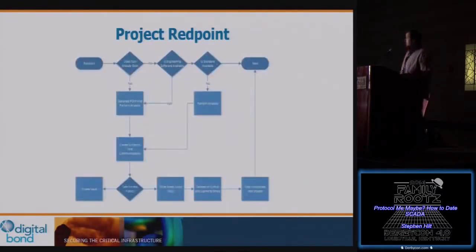Sorry. To do this, there's a couple of methods we use. We look to see if there is already a pre-existing tool that is doing it, and then we can just convert it into an Nmap script. We will look at the applications themselves, if we own it or somebody we know owns the engineering workstations used to configure the devices. We'll grab packet captures and do some analysis. Or sometimes we will actually just read the standard and reverse it based off the standard.